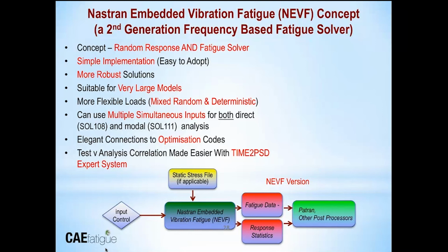And that could be done for both modal, solution 111, and direct. And I should also say it's also totally okay to do it for static analysis problems. So just because you're working with a static model doesn't mean that this process won't work. We've also done a lot of work with optimization that I'm not going to talk about today, and we've done a lot of new work with the load conditioning time to PSD expert system that I talked about.